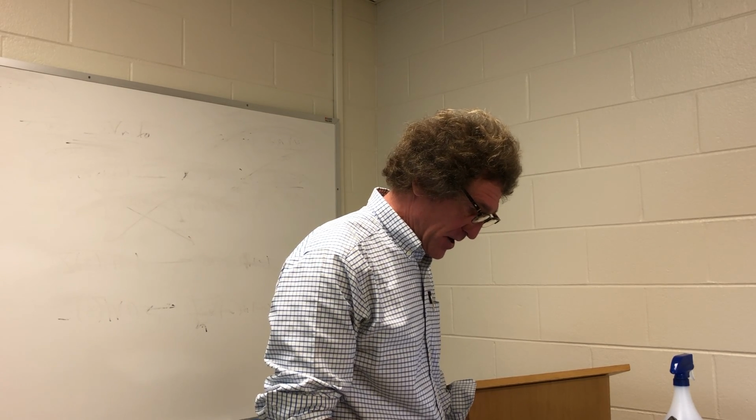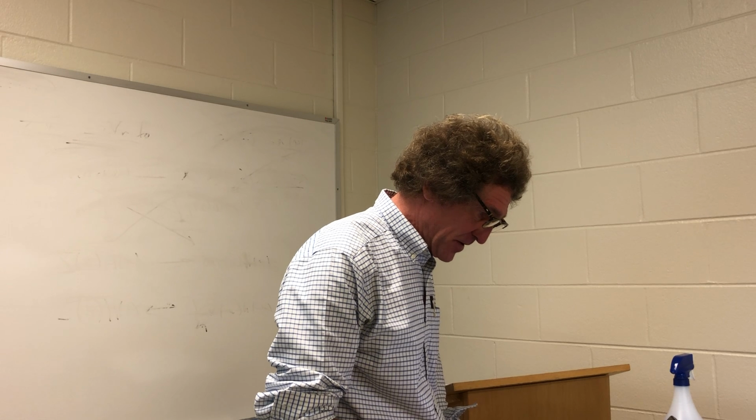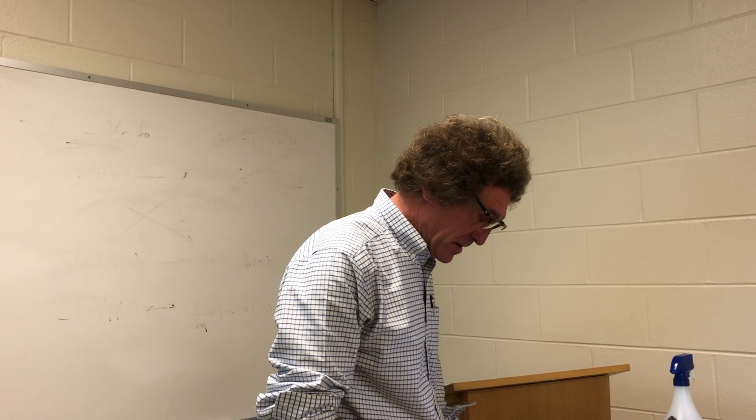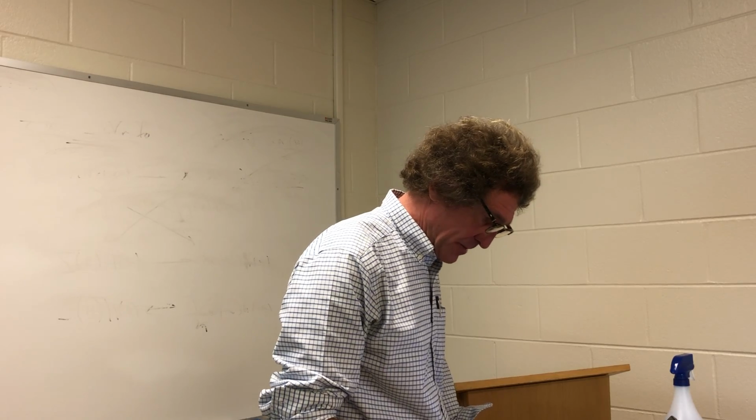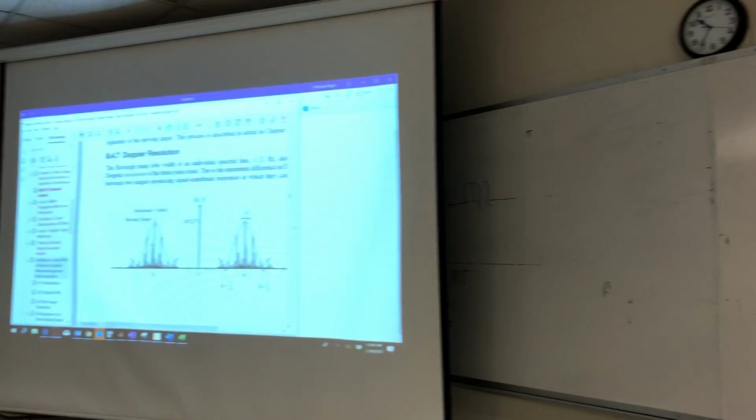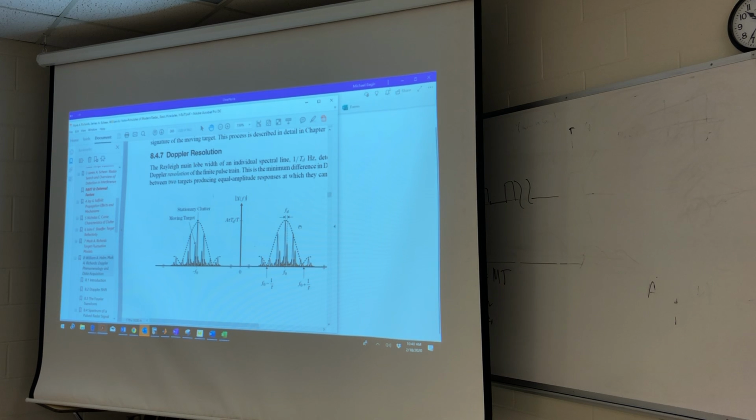All right, now I'm going to try to show you this. I got to amplify this or blow it up a little. If you have it open, I know there's a couple of laptops here, bring your laptop. What I want to show you is what happens when you get a target moving, when you're sending and receiving a signal. Now he's not using a match filter, this is raw data. This is what you'd see if you just did the Fourier transform, and it's in continuous time. It's not what you're really going to see, but it's giving you a picture of what goes on.